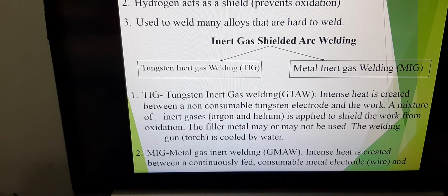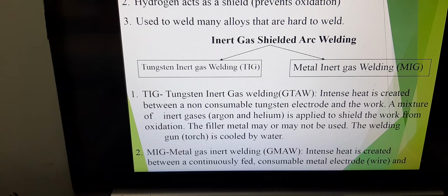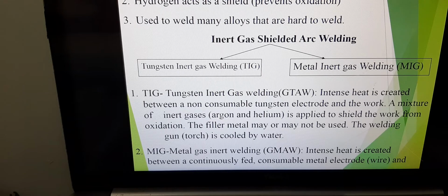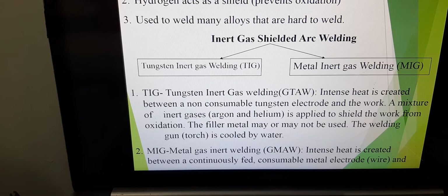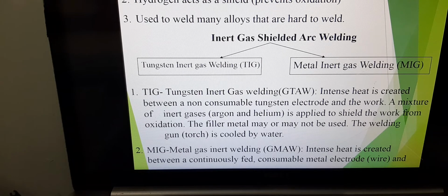If you remember back in unit 4, we spoke about metals, and I told you there are two categories of materials, the brittle and ductile. You have the overly ductile material and the overly brittle material in the extreme cases. So if you're dealing with an overly brittle or overly hard material, when machining is a big challenge, welding is also an equally big challenge. You would need very, very high temperature concentration in order to weld this kind of material. So there you have atomic hydrogen arc welding to assist you in this kind of welding process.